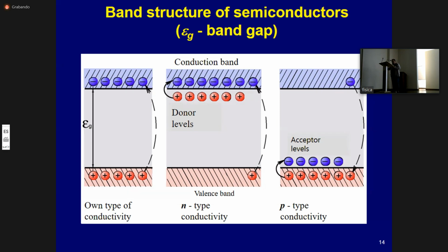The depleted layer of a semiconductor detector is created as follows. A layer of n-type substance, with electronic conductivity, is deposited on the surface of a p-type semiconductor, which has hole conductivity. By diffusion, electrons from the n-type semiconductor will be introduced into the p-type semiconductor, and holes will go in the opposite direction. Similar reasoning can be carried out if a layer of p-type substance is deposited on an n-type semiconductor.